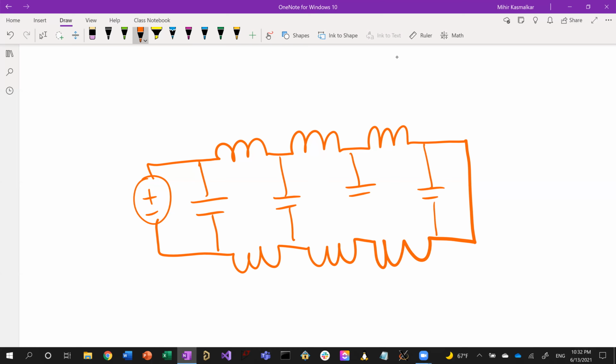And so you have a short circuit at the end there. Let's trace the voltage and current wave. I'll just draw the voltage wave propagating forward. Once you reach the end, you see a short circuit where there's by definition 0 volts. A short circuit is where you can have some current, but 0 volts across it.